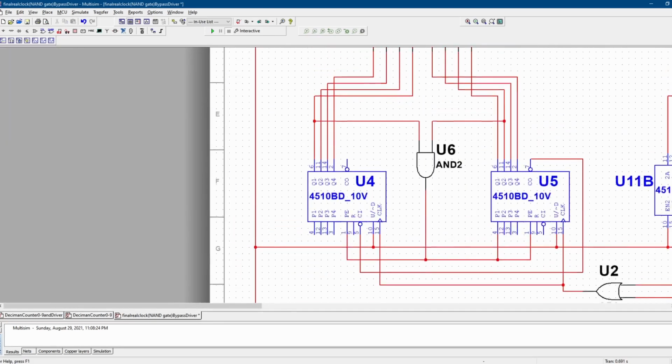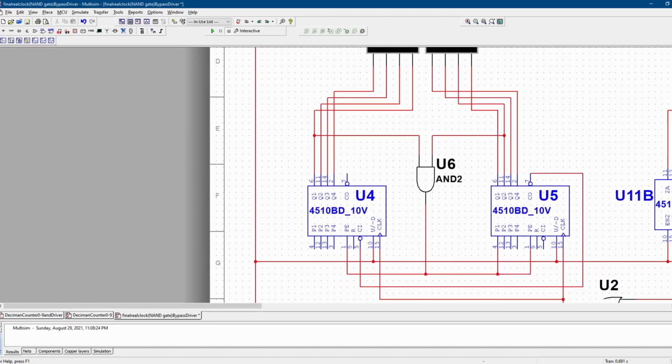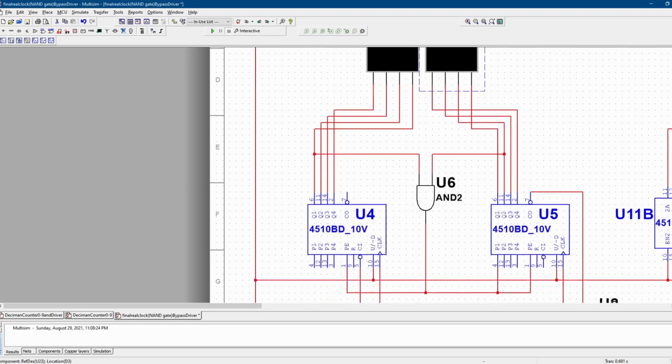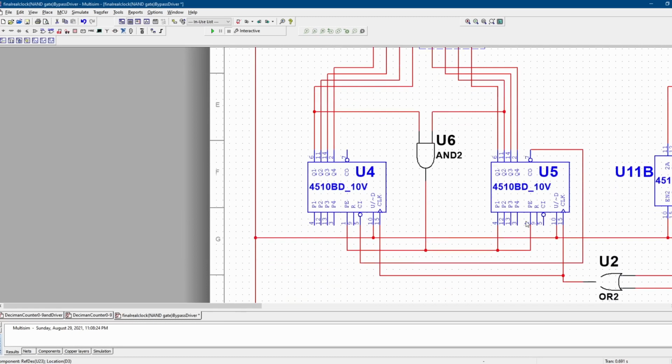So this is what will allow the counter to go from 1 to 12. Okay? This will go from 1, 2, 3, 4, 5, 6, 7, 8, 9, and then we'll have 10, and then we'll have 11, and then 12. And then the preset enabled is activated, and then it goes back to 1 because of this line here.